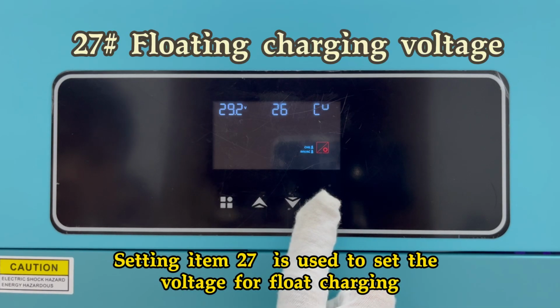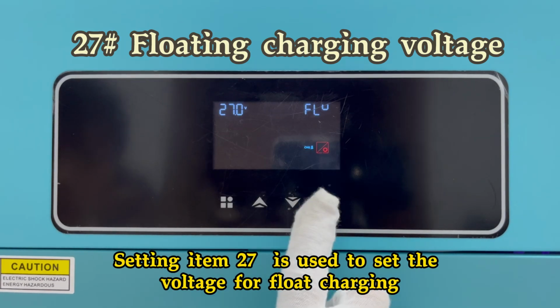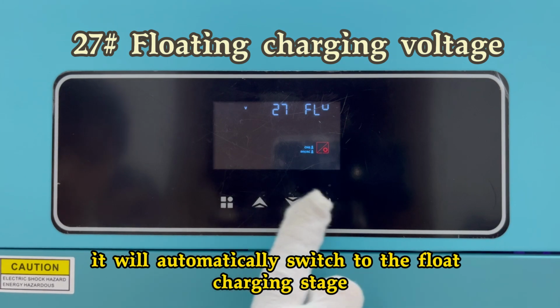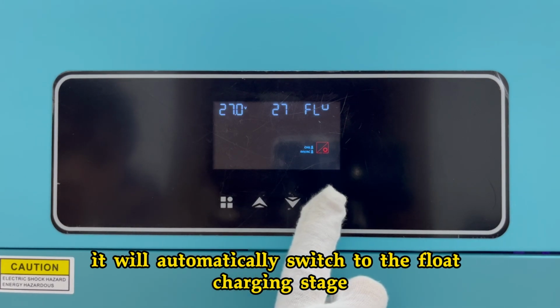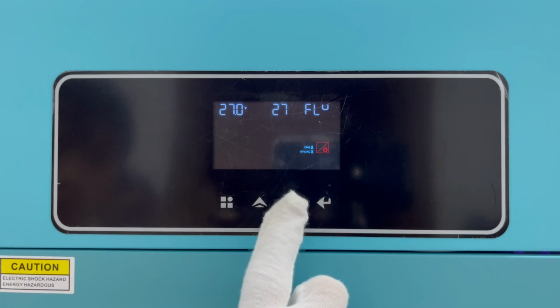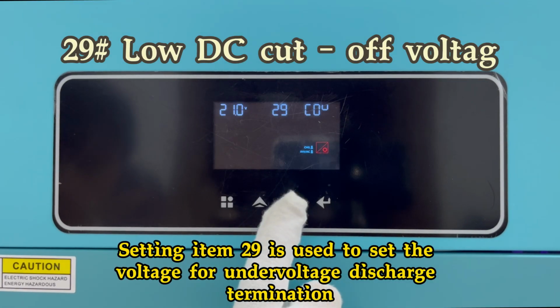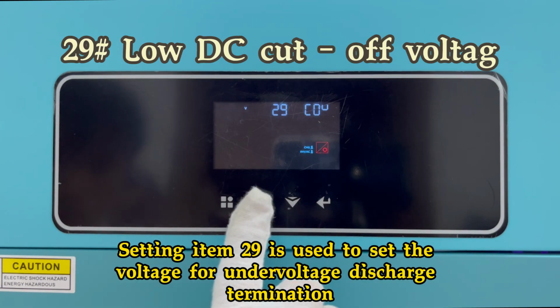Setting item 27 is used to set the voltage for float charging. When the battery charging voltage reaches this value, it will automatically switch to the float charging stage. Setting item 29 is used to set the voltage for under voltage discharge termination.